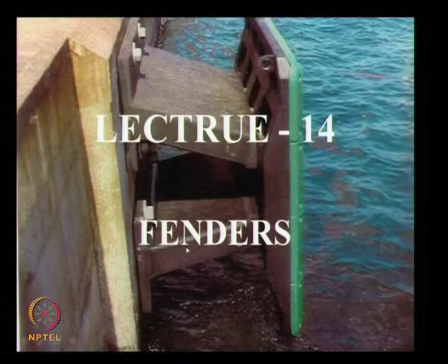In this class we will discuss fenders, this buckling type fender. This fender consists of this rubber component, then we have a frontal board. This part of the black color is a steel board, where what we see here in this green color is a rubber board which will reduce the friction between the vessel and the fender. We are seeing the bolts here which are used to fix the fender to the berthing structure.